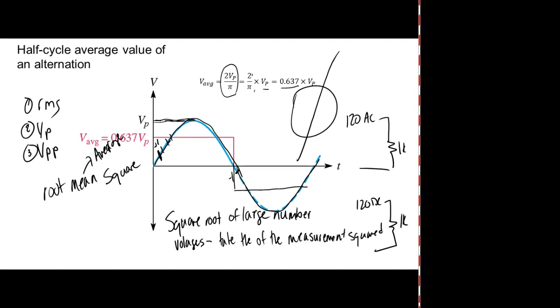What happens to the sign of the number? It turns positive, right? Y'all understand that? If you square a negative number, it becomes positive. So what we're doing now is we take the mean, and we're taking the mean of nothing but positive numbers. The mean is going to be a mean of the squares. So what do we do? We take the square root of the answer, and then that gives us the effective voltage.